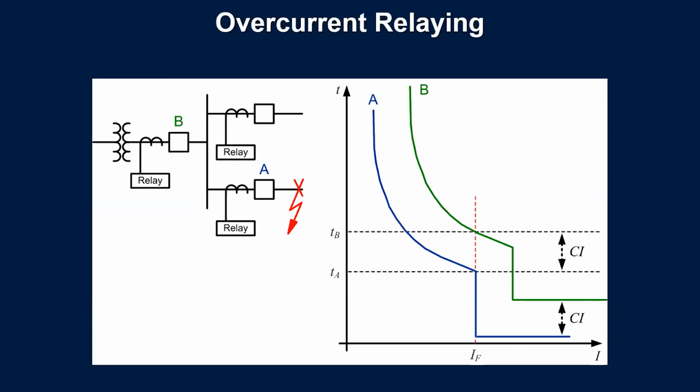We have to be able to assess the risk. You can see from those equations that assessing the risk, coming up with the amount of arc flash incident energy that could be present, is a complicated task itself. But like Gotham showed you, no matter how complex any of those equations get, time turns out to be the easiest lever we can pull to adjust the available arc flash incident energy. And that's great for us because no matter who you are, where you are, what your installations look like, you've got some sort of protective relaying there. We're going to talk about some SEL solutions, but honestly, some of these solutions can be employed using just about anyone's relaying.